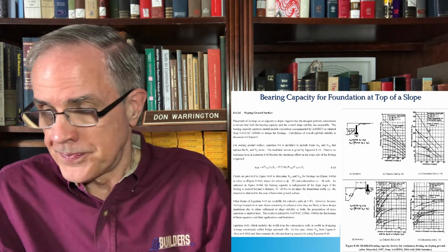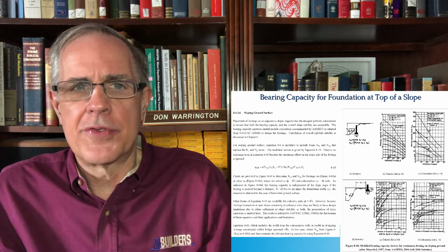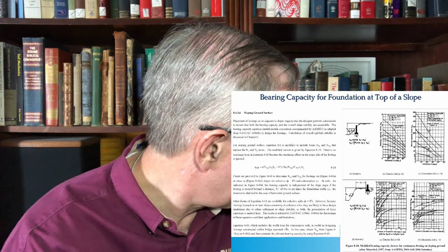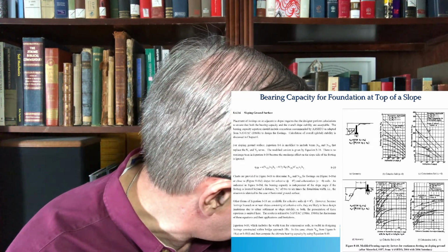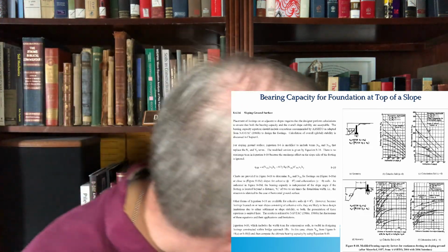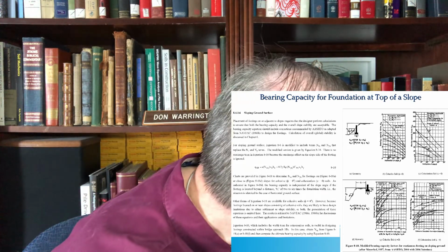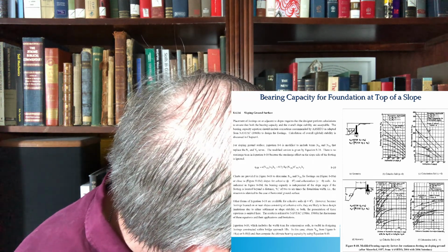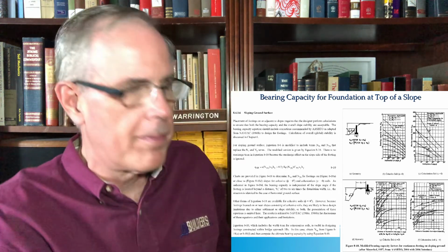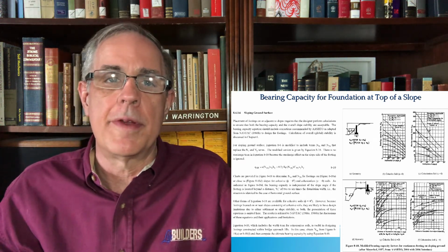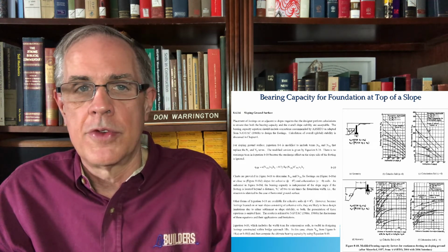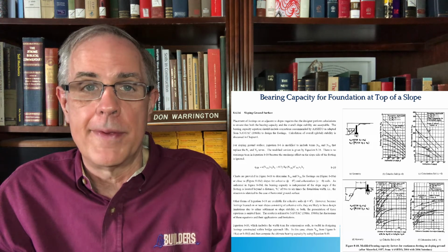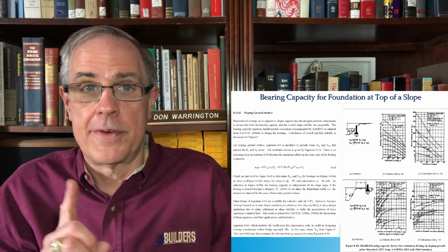So basically the trick behind this, and I want to concentrate mostly on this case, is that these charts are based upon this axis, which is the distance of the foundation from the base of the slope, and which it is depends upon how you compute your stability factor. So the first thing you need to do in any of these problems is determine your stability factor.